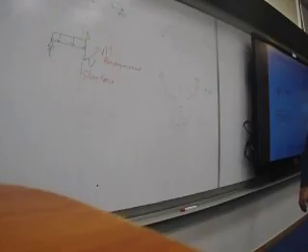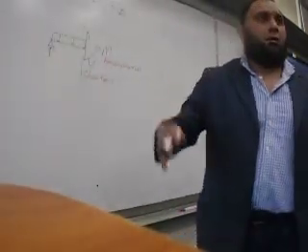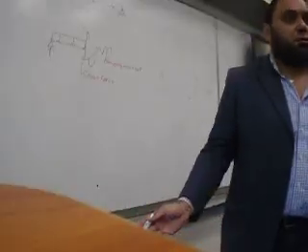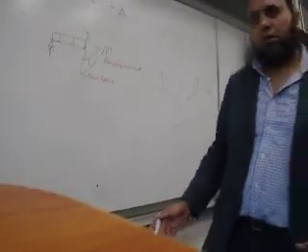Supposedly, if you do the same calculation from the left hand side, you'll get exactly the same result as the right hand side. So it's the same one. Actually, this is one of the checks that we do: you take a cut and you look left and you look right and you reach the same answer. So this is something that we'll do. Okay, let us do the example now.